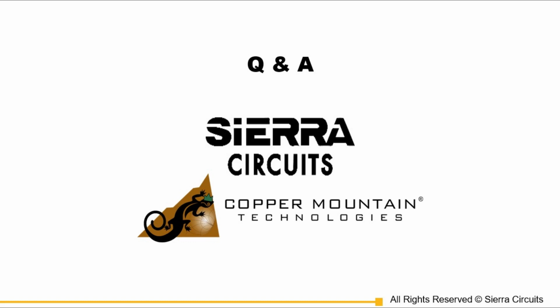Yes, there's all kinds of changes that happen when you go from horizontal to vertical on the PC board. What I have seen is that you would have a central via for your signal, and you would build a radial fence of vias around it to try to create a sort of coaxial 50 ohm line. It's very difficult to do, and the only way you're going to pull that off is to do full EM simulation of some kind. So yes, it can be done, and it can be done well, but it's not easy.